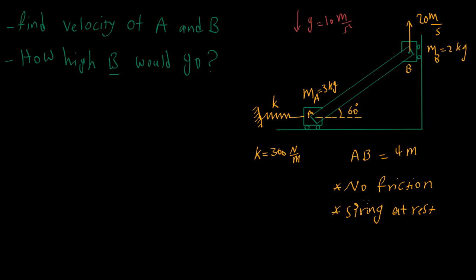So basically, because we also don't have any friction, here we have the conservation of energy. This is a problem in that category. So here we would just say that T1 plus U1 is equal to T2 plus U2. Or you can start by writing down the W of non-conservative forces is equal to E2 minus E1, energy, both kinetic and potential energy. And then argue that the W of non-conservative forces is 0 here. So we have the conservation of energy here.